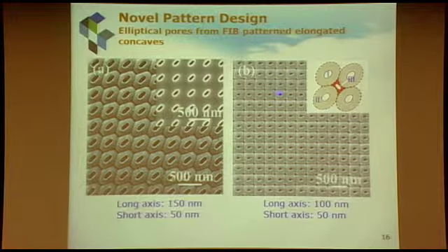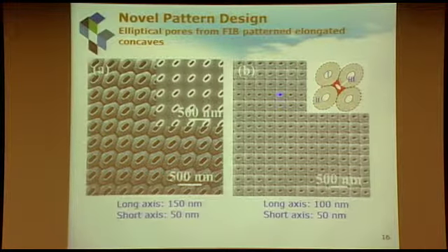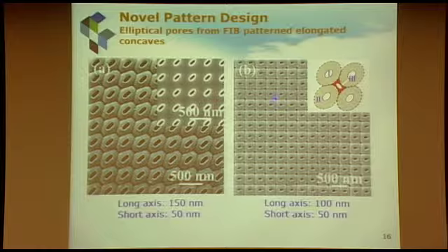This all actually goes back to a very simple reason, which is the oxide layer formation process. These pores, they are kind of in this direction. They are closer because they are longer in this direction. So the oxide layer for this small pore, it cannot grow in this way much. They are confined. So in this direction, these pores are further apart, and then the small pore gets more chance to grow in that direction. So as a result, you can create all kinds of pore distributions. This just show you the process.